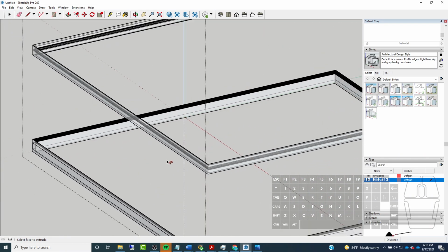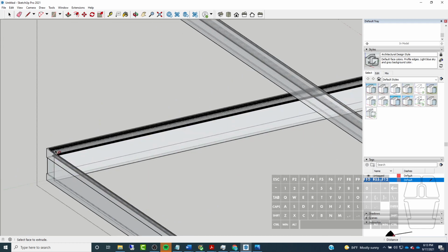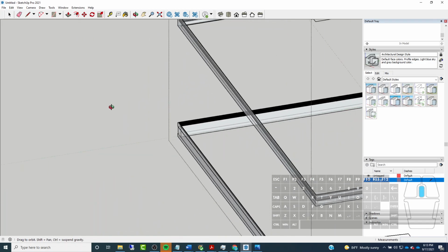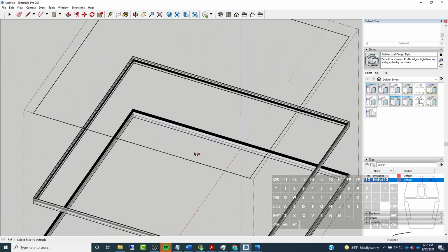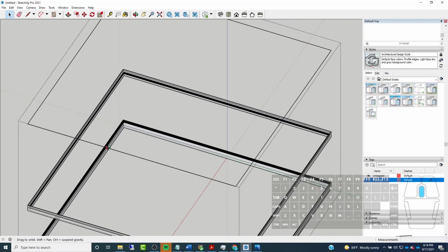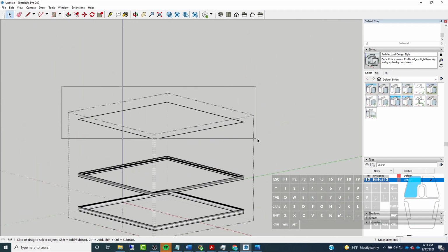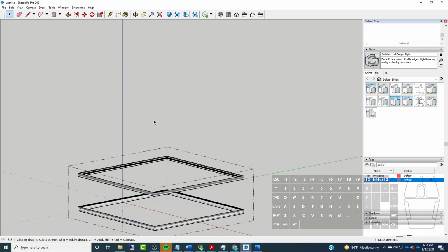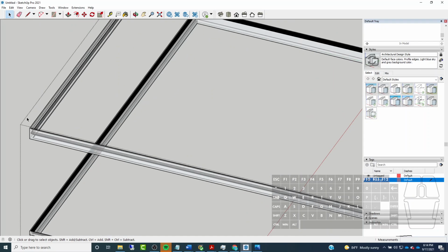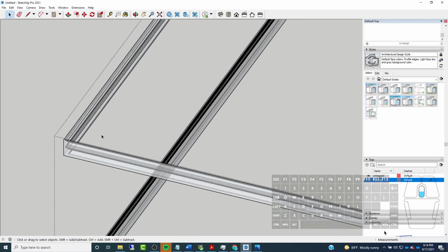If you're doing really complicated geometry, like this is kind of complicated, it gave me that little error message, but you just got to look at it and make sure it looks okay. And in this case, everything does look okay, so that can just be ignored. So now I can just go ahead and delete out my path and do the same thing here where I am smoothing out all of these individual line segments.